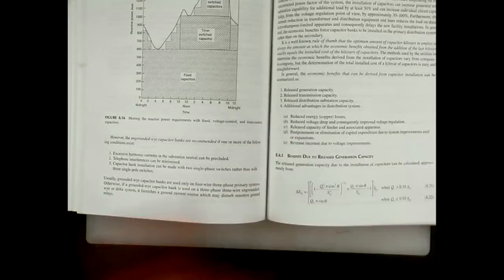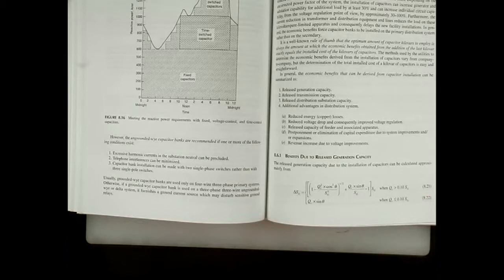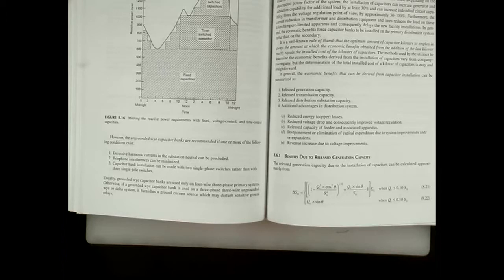Now, it's very hard that by just doing power factor correction, you can fix everything. Revenue increases due to voltage improvements. I don't believe that. Well, I don't know what the author is thinking of that, right? So if your voltage goes from 95% to 100%, what's going to happen? Right, exactly. More power out of the load, right? Because the voltage is higher. When you calculate the current, what do you get? More current. But that's assuming that you have a constant resistance or a constant inductor, right? So if you increase the voltage, the current increases. If the current increases, what's happening? Your kilowatt-hours increase, right?